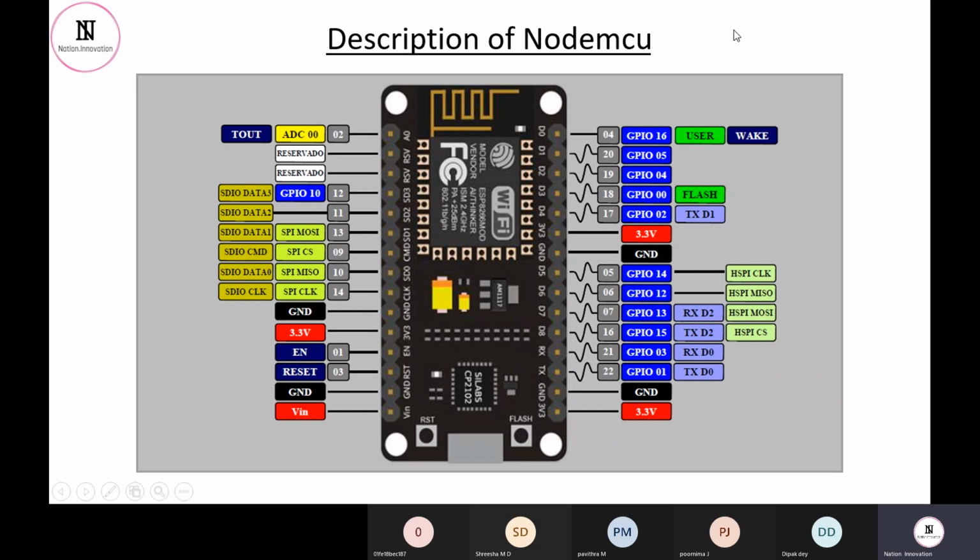Use just 4 of the digital pins as select pins for the mux system and put the sensors as inputs to it. You can interface 16 different sensors with 4 pins, just by changing the timing, the time at which we take the value. It can be a 50 millisecond delay, 10 milliseconds, or after 1 microsecond. So by using this functionality, we can increase the availability of analog pins. So if there is a disadvantage, we have some solutions for that as well.